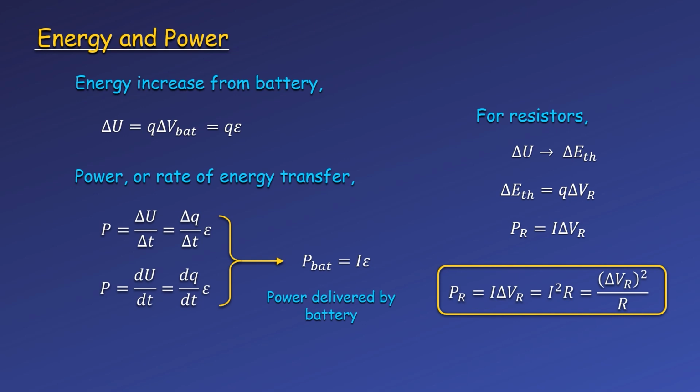We want to provide power or energy at a particular rate to homes and businesses. Because energy is conserved, we can only provide the power that we generate, so we don't want to lose any. The higher the current, the more energy that we lose to heat and cannot use to power our homes and devices. So looking at the formula current times voltage, we can keep the power the same by lowering the current, but increasing the voltage by the same factor. This means we're able to transmit large amounts of power over long distances with little loss because the voltage is high and the current is kept low. This is why we cannot ignore energy and power of circuit elements and other devices. They play a large role in our everyday lives.